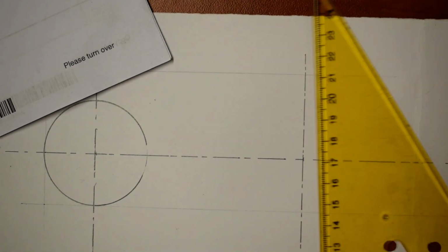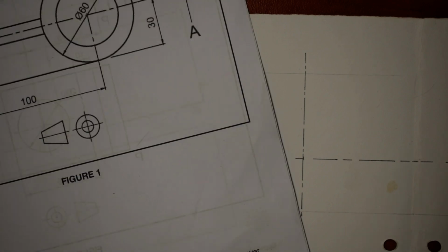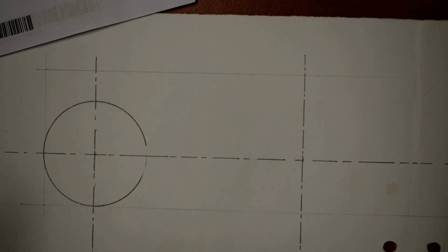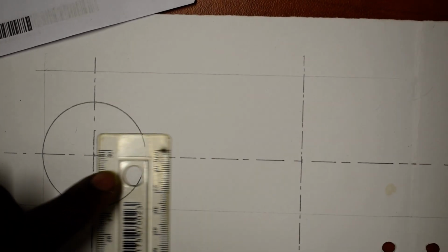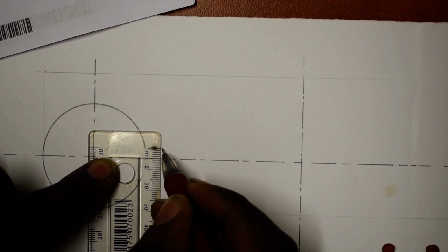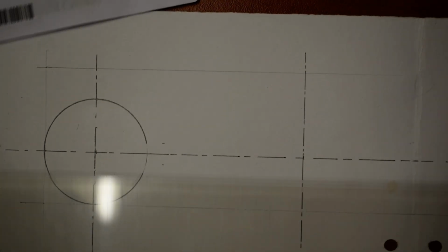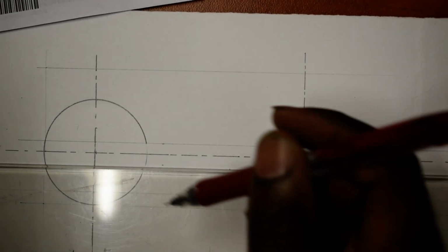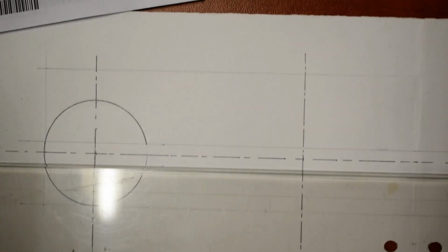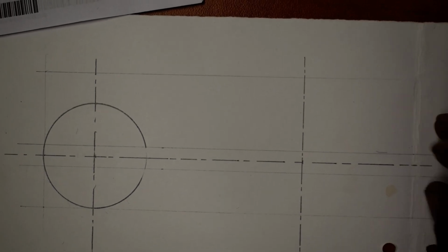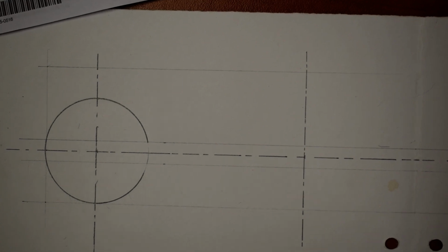This, you get it? So from there, what is going to happen now? So I can see the thickness of 10 millimeter. Okay, the thickness of 10 millimeter. So I can simply say 5 this side and 5 this side, isn't it? So that I mark at 10 and mark at 0. You get it? So I draw a horizontal line. There you go. So you take it a little bit faint towards your right hand side. Remember about your left view.